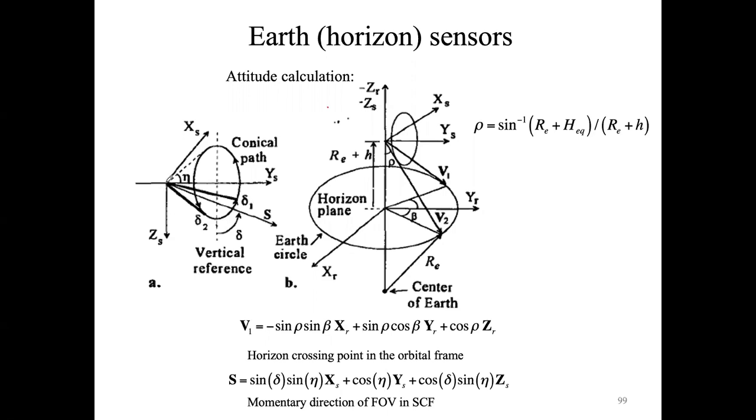This instrument, after that, is placed in the reference frame of the spacecraft. So now this reference frame here is placed in the center of the spacecraft, and we need, as we've done for previous problems, to determine the attitude of the spacecraft with the specific reference frame. What we've done for star sensors, and in general by using the TRIAD and QUEST problem or the extended Kalman filter, we assumed that the reference frame that we want to use was indeed the inertial reference frame.